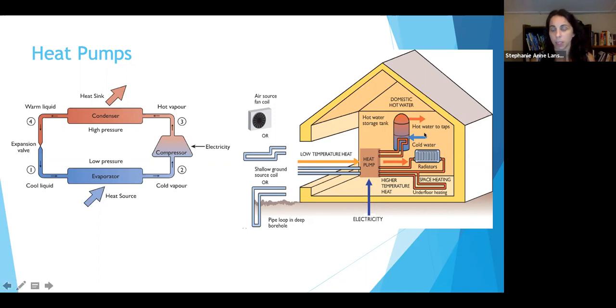And so again, we can actually tap this into our existing radiator, space heating, hot water, so that we can either use it as our only heat, or we can just use it as an energy efficiency process where we're basically bringing in the temperature at a higher level in the winter, lower level in the summer. And so we are increasing the efficiency of the system by using the same concept we use for refrigeration, the heat pumps, but using it based on the ground temperature.